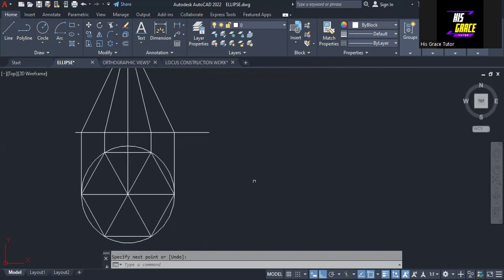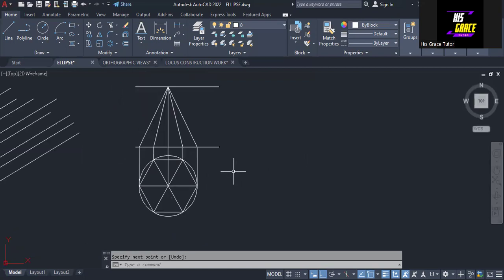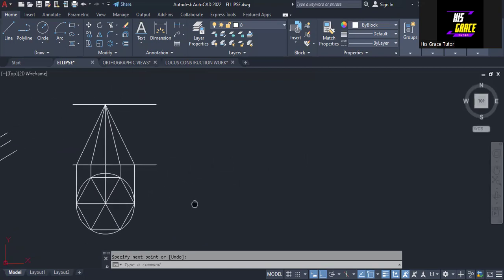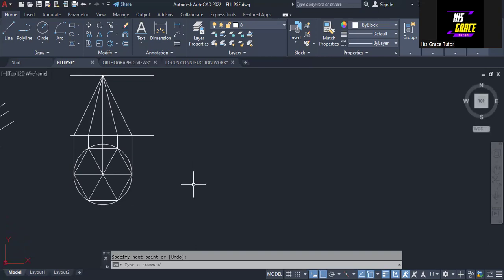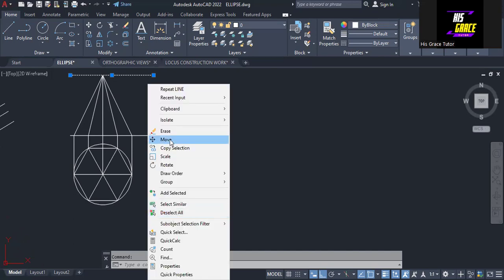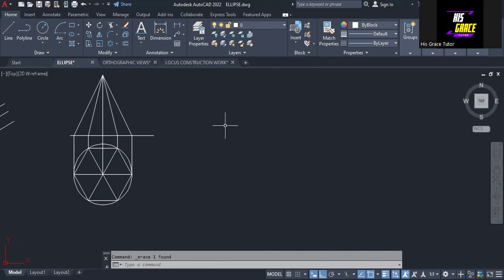I want to draw the auxiliary plan, as we have said at the beginning that we are going to draw the auxiliary plan of this pyramid. So that's what we want to do here. We need to make sure we know the angle at which the object is being viewed. And that angle, I'm going to make it 45 degrees.